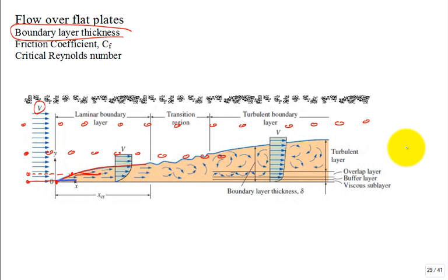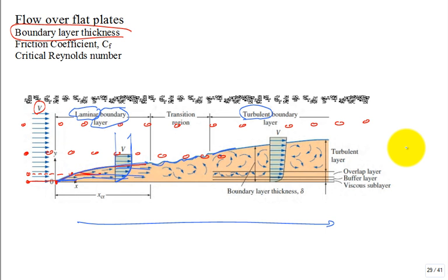And then you have this profile where the velocity goes toward free stream, and it's back to free stream out far enough away. So you have a region that develops, and they call that the boundary layer region. At first it's laminar, and then after a while, if the plate's long enough, the competition between inertial forces and viscous forces in the flow field could make it transition to a turbulent boundary layer. When it does transition to turbulent, it grows at a different rate than when it was laminar. And what are they showing with these arrows? Instead of the arrows always being nearly linear, parallel, you have them going in all sorts of mixing.